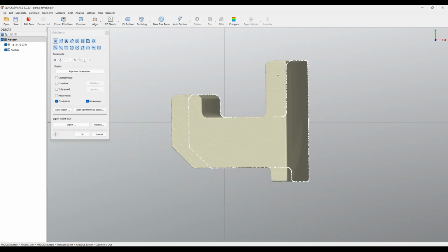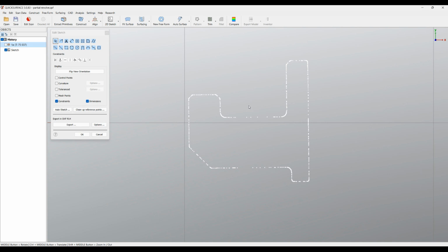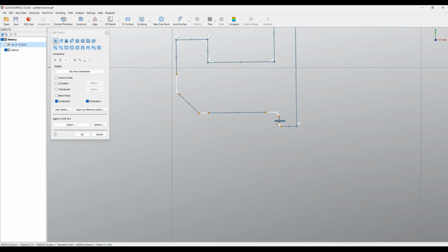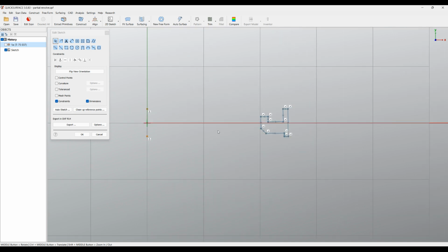The reason you see the mesh like this is because it's a revolved surface and it's actually turned around, and that's why you see the shape as it is. But I am not interested in the mesh at the moment. We'll quickly hold Control Shift to extract my lines like this, and we'll intersect my profile by using only the control and brushing over the corners. This will help you quickly close your sketch. And so far I created my profile.